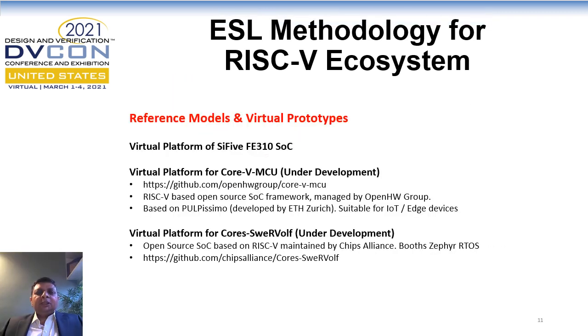We are also developing the reference IP models and reference virtual platforms. We already have a virtual platform for the SiFive FE310 SoC and we are in the process of developing the virtual platform for various open source SoCs like CORE-V MCU from the OpenHW Group or the SweRV EL2 from the CHIPS Alliance. So these reference IP models and virtual platforms can act as a very quick start for developing the model for any RISC-V based SoC.